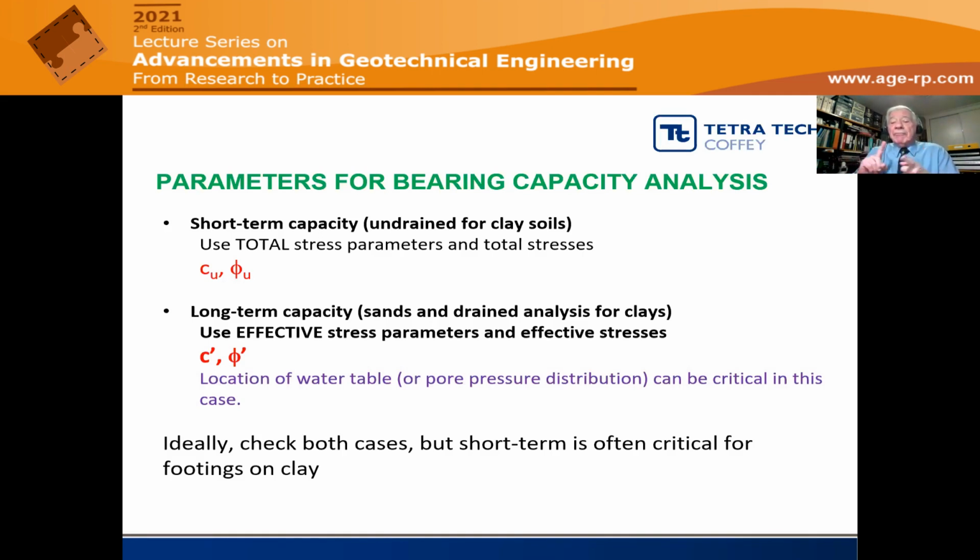Just be careful, however, that this is not a universal rule. If you have a situation such as you have with excavations, where you have a reduction in stress over time in a clay, so that when you excavate a clay, you're actually reducing the stresses in the clay.